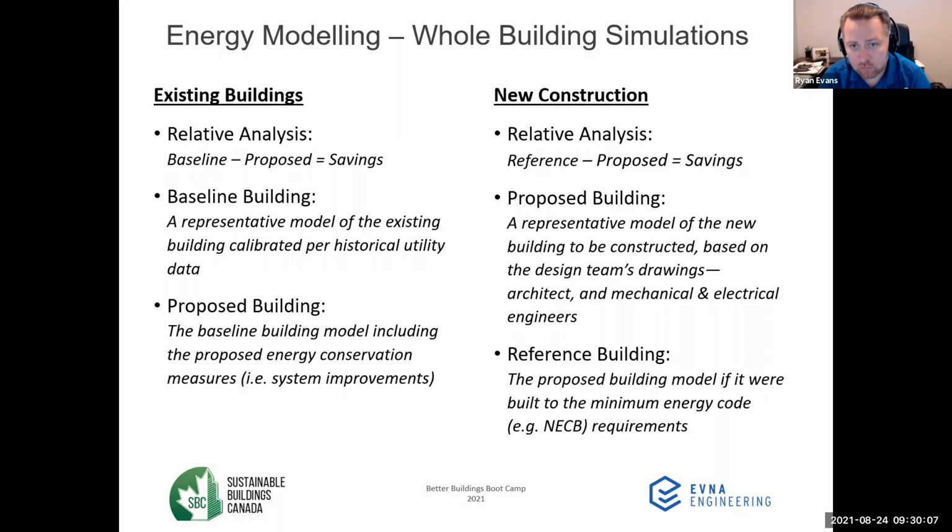We can do them incrementally, which gives us a little bit more visibility, so one measure at a time. But then you also need to do an analysis of the aggregate of your measures. So I'll give a little bit of an example of that. If we're interested in improving the lighting system and, let's say, the heating system, okay, we're going to change the boilers. If we do an analysis just on the lighting system, it's not going to really take into account the impacts on the other systems.